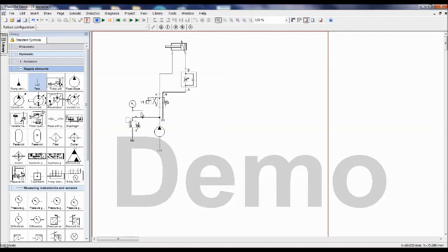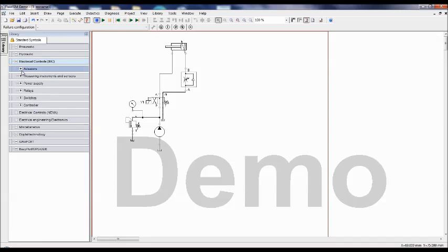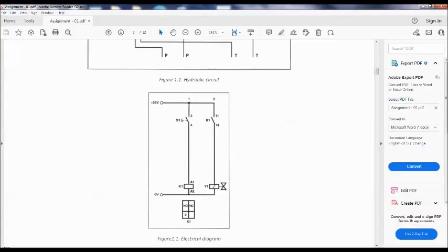Now you have to take the IEC standard electrical controls, their power supply. Since the operating voltage of the solenoid is 24 volts DC, we have to take a 24 volts DC supply. Look at the diagram here. There is one normally open switch, called S1, and it is connected to a relay box called K1. The relay box will have a relay coil and then contacts. Coil and contacts together form a relay unit. So we are controlling solenoid Y1 with the help of the switch through the relay. That is why we call it a relay circuit.